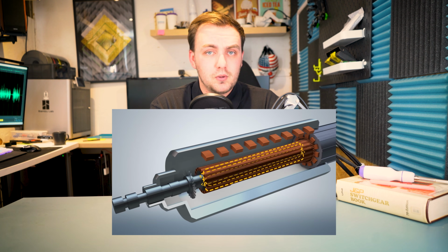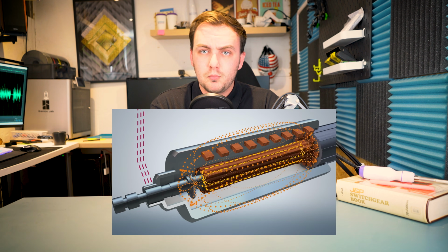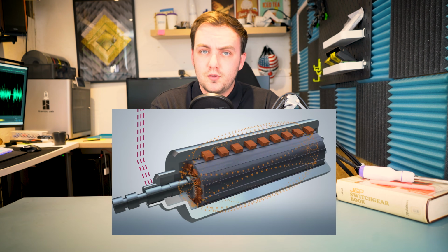These generators were able to produce lots of reactive and real power. However, now that we've moved to predominantly renewable power sources, these come with their own challenges regarding reactive power and balancing the grid. For example, solar panels produce direct current, which must be inverted to alternating current to be put on the grid. These inverters produce only real power and traditionally no reactive power, meaning they couldn't support reactive loads on the network. However, modern smart inverters are much more capable.